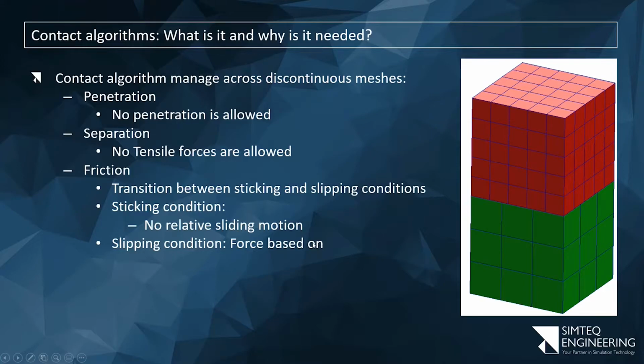And then we get to that classical equation that says the friction force is the normal force multiplied by the friction coefficient. Before that, it's simply sticking. That friction force, the friction coefficient multiplied by the normal force, is a limit for this. It cannot exceed that value initially when it's sticking. But the moment it transitions to slip, and then it starts moving.